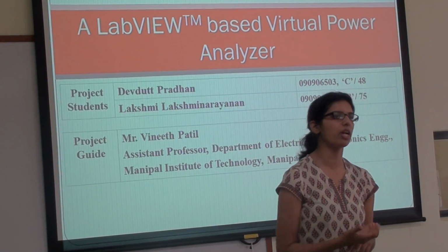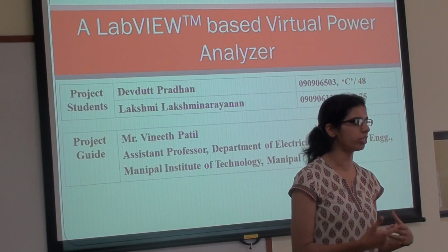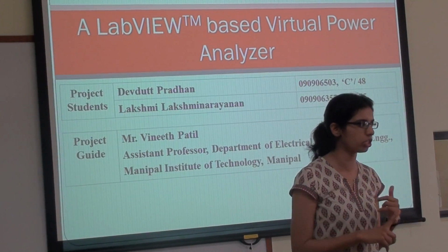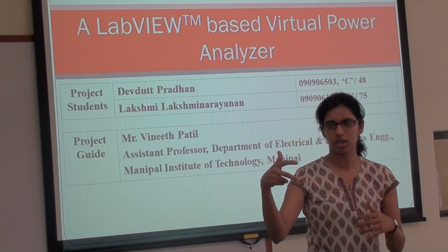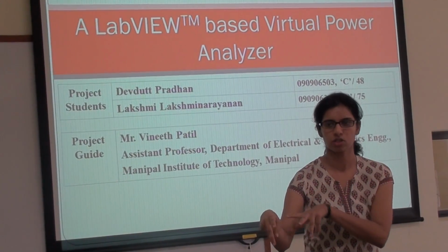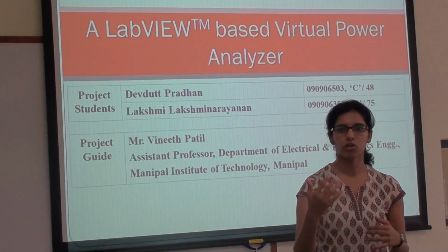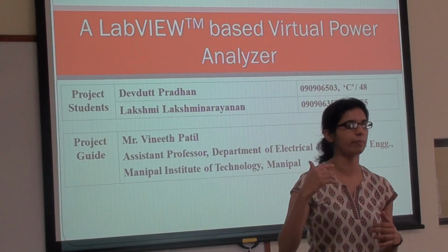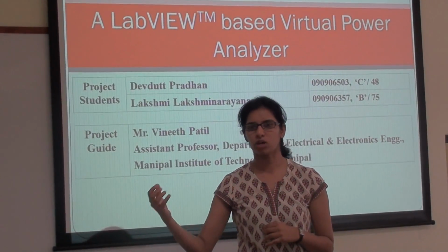Now, where does a power analyzer come in? It's basically an instrument that is used to monitor power quality parameters like your voltage, your current, and the quality of power that's coming in from the supply or across any terminal that you connect it across. It gives you the value of, like I said, the voltage, the power, and it also helps you determine if there is any particular sag or swell. These are just events that occur in any power quality system.